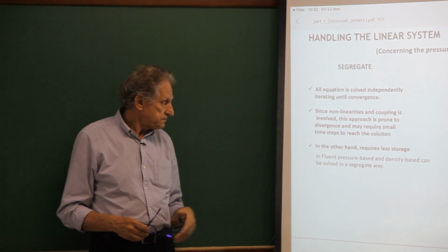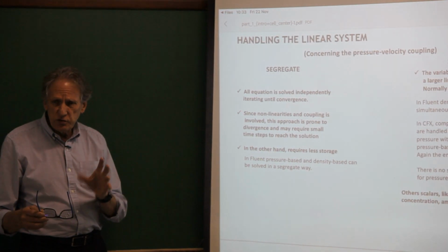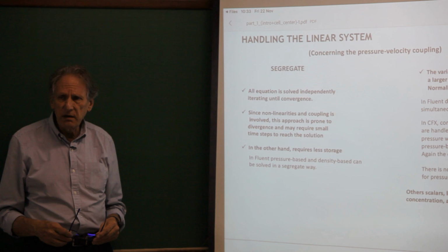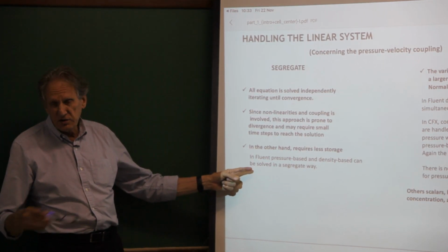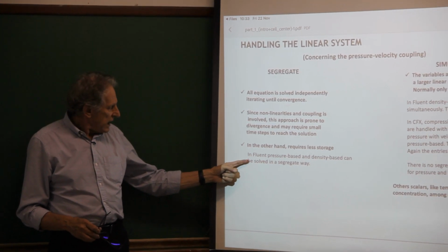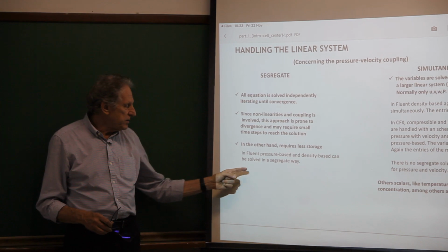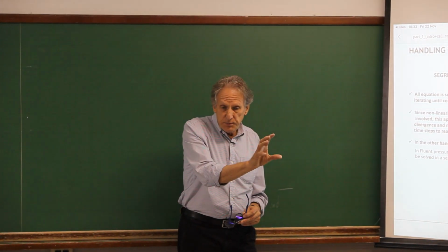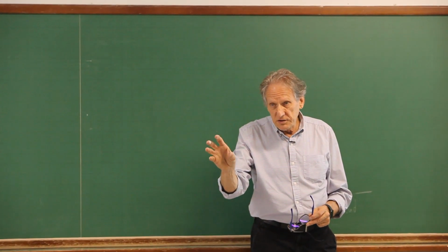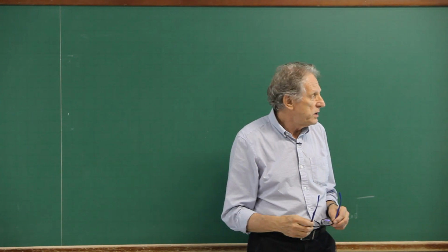But, you know, this is more difficult to solve when it's in the segregated fashion. I put here some observation because these are the software that I know. In Fluent, pressure-based and density-based can be solved in a segregated way. If you go in Fluent software, there is the pressure-based, there is the density-based, both can solve in a segregated way.